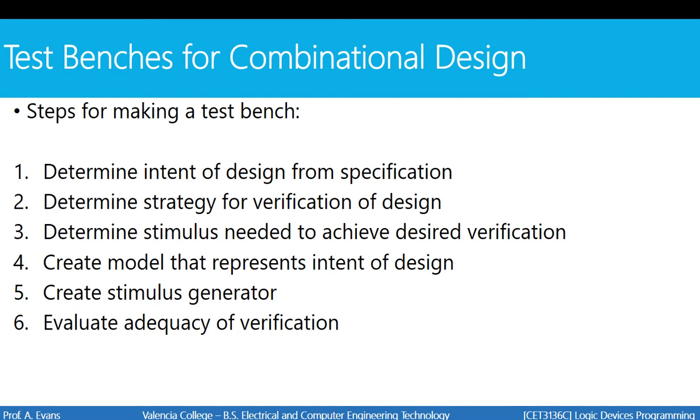Then you need to create a model that represents the intent of the design. The model is what we're going to be doing today. Create the stimulus generator, which means to simulate your model or run your model in a program. We're going to use ModelSim to run that program today, and then use the output of our test bench to evaluate the adequacy of our design.